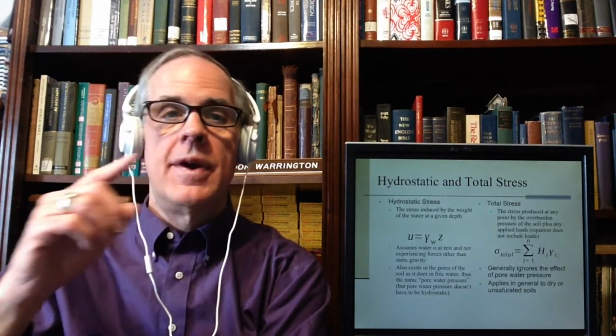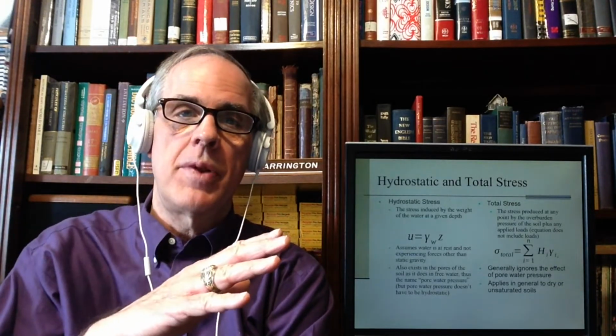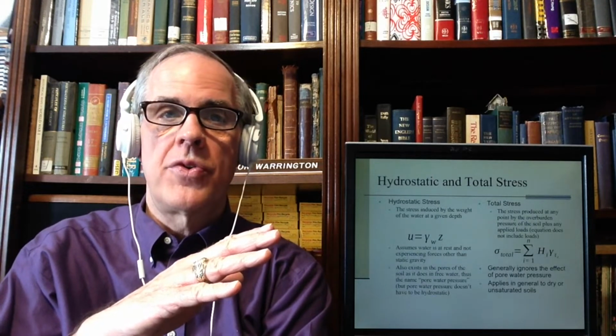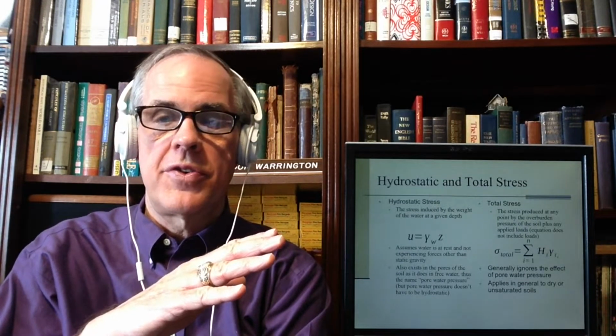I say it ignores the effect of pore water pressure. It does not ignore the effect of pore water weight. Pore water weight definitely enters into it, because as we saw the last time, pore water weight is a part of the soil weight. But we're not talking about pore water pressure just yet. It applies in general to either dry or unsaturated soils. It also applies to soils that are saturated and anything in between.